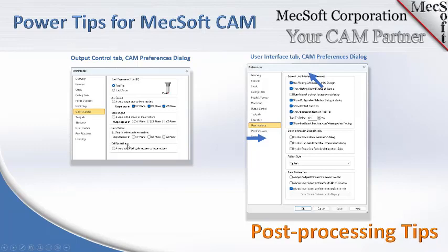If your CNC machine does not support what's called canned cycles, canned meaning that there are predefined drilling operations in your controller, we can call those when we G-code a drilling operation, for example. We can tell it the code, and it's just one line of code that has all of the information needed to drill that hole.